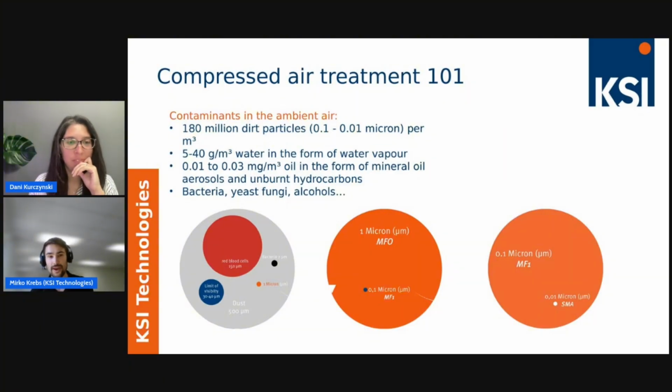So we want oil-free air. We need to make sure that all the oil that we get out of the compressor or out of the ambient air, that we remove that. So we would recommend using an activated carbon tower, and the reason is that aerosols and oil droplets you can filter out, because those are drops of oil in the air, so you can coagulate them and remove them with the condensate, but what you cannot filter out is oil vapor.